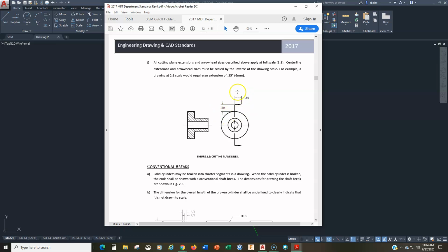So you can see we got some suggestions for the section line, location of the arrow. Now the 0.5 off of the object and the 0.5 for the tip, these are suggested, right? Because a lot of times the dimensions get in the way of that. So work with this as a first stab and then adjust accordingly based on the dimensions. You might need to move dimensions. You might want to extend this slightly, 0.75 or whatever.